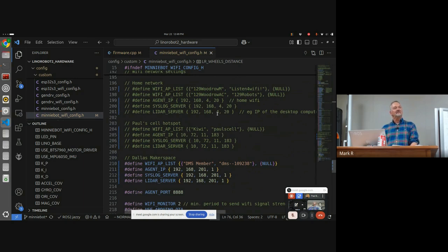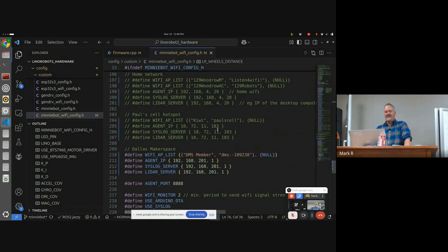In a normal robot program, you would configure a robot block, and that would have all your pins defined. If you don't want any magic numbers in your code, that's what it should be. And then you have all your functions separated. If you're using C, you separate them into separate files. You'd have a motor function file, a sensor file, and so on. So this is just good practice.